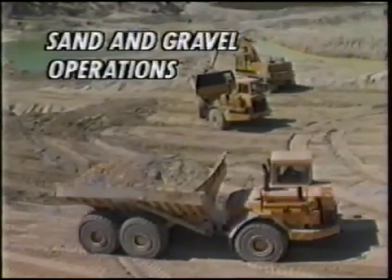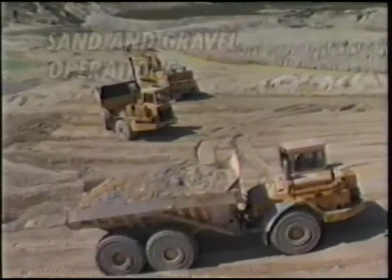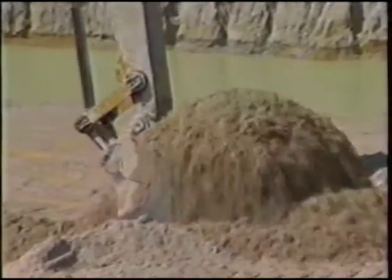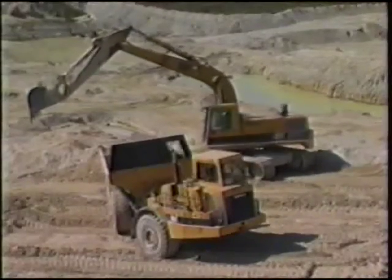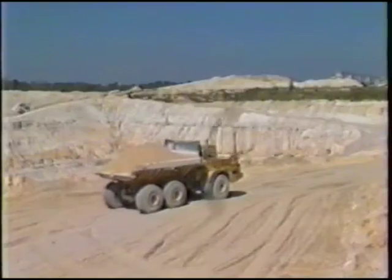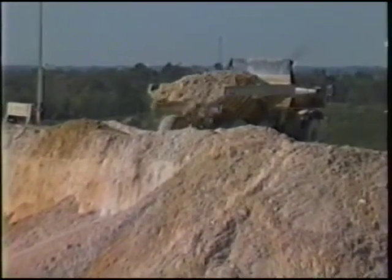For sand and gravel operations, the next step after stripping is loading and hauling the material to the raw feed hopper. Because of the loose nature in which these deposits are found, it is not necessary to drill and blast. Hydraulic backhoes and shovels are commonly used to load sand and gravel from the pit face into off-road haul trucks for transporting to the surge pile. At some operations, material may be dumped directly into the feed hopper.